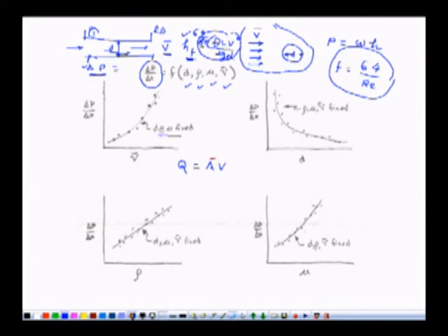If we know the diameter of the pipe, then A is known to us, and we can find out velocity, right. So, we can plot this graph, and with the help of this plot we can say what is del P over del X for different velocities, and we can answer this question.